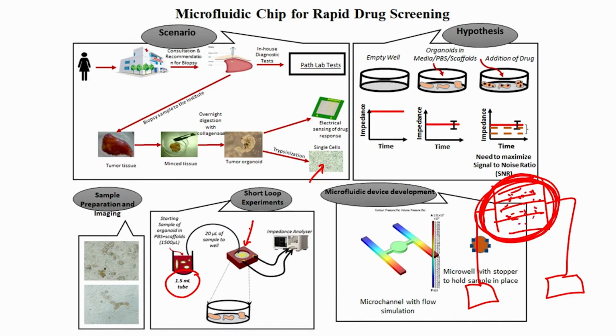I will put cells on this particular chip with some material. What will happen initially when there are no cells is that my impedance is infinite. When there are some cells, I will have some impedance. Let us say I have 100 kilo ohm impedance value, alright, Z equals 100 kilo ohms, and Z equals infinity when there are no cells. When I place the cells, my Z becomes 100 kilo ohm. Now, if I load a drug on this, if I load drug 1,